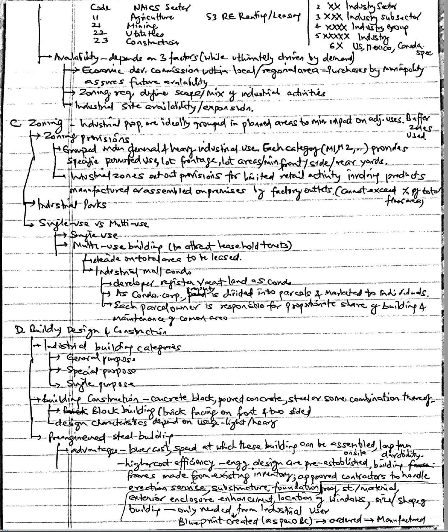Bay depth refers to the distance from the bearing wall to the rows of columns in the building, or the distance from one row of columns to another. Bay depth is an important consideration in the layout of office, retail, and industrial buildings. In retail and office leasing, the term takes on a precise meaning when referring to bay measurements in the construction or outfitting of office space. The bay depth refers to the measurement from the outside wall to the inside corridor, or from the exterior wall or glass. Bay depth is important in deriving the most efficient use of space, as is the bay height.